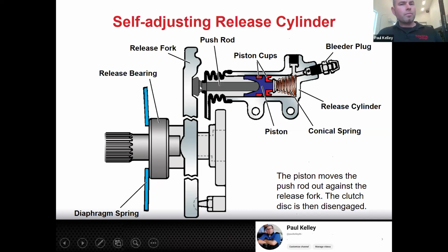So sometimes, this is what I saw. This was like a pro tip, a life hack for you. When I did the clutch on mine, my mentor came over and he was pumping the slave cylinder from the bottom. I was like, what are you doing? He said, this is going to help bleed it. I was like, why? Well, it made sense now. If there's any air trapped up against this piston, and you come down here and basically stroke that slave cylinder, you break that air free and get it over here while you're bleeding it, and it'll help get all the air out.